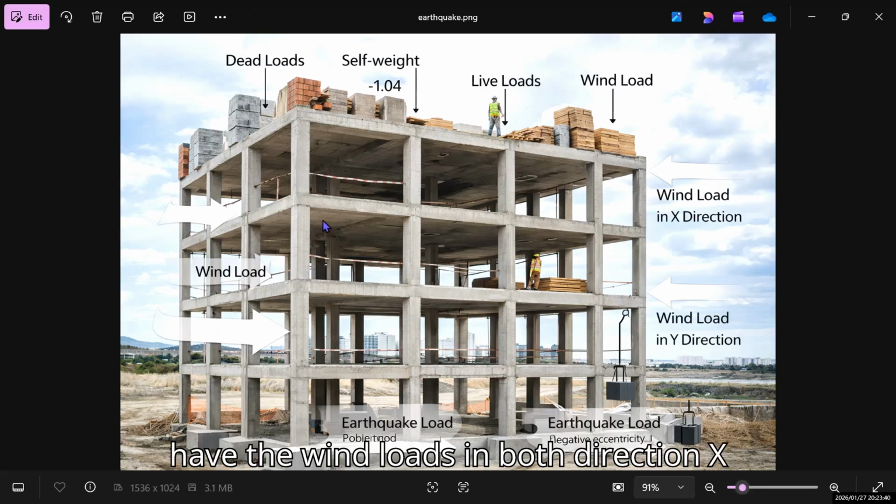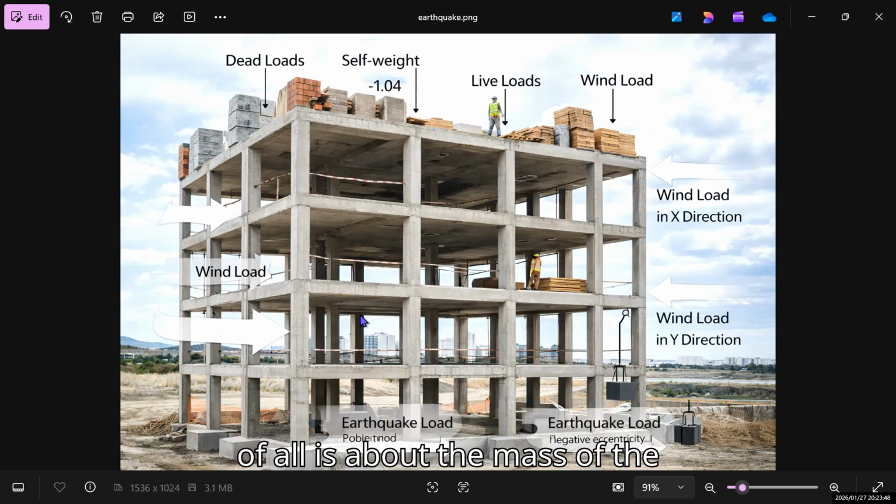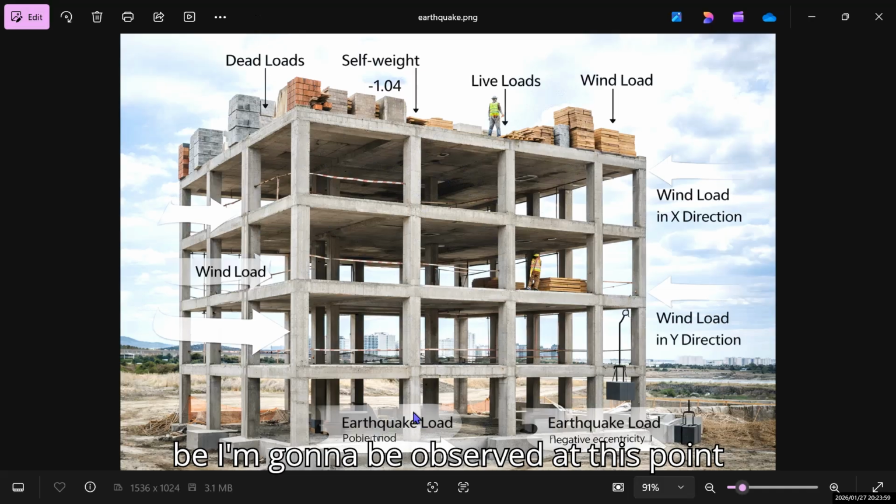Then we also have the wind loads in both directions, x direction and y direction. We also have the earthquake. The earthquake is mostly about the mass of the building, and it's applied at the eccentricity of the building, like on these columns. The earthquake is going to be applied at this middle point, in both the positive way and the negative way. So we're going to have 4 eccentricities of earthquake.